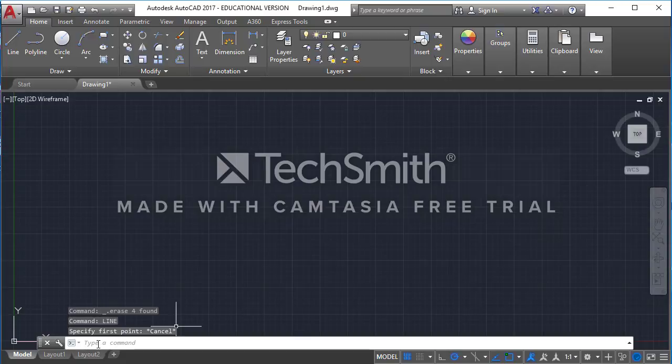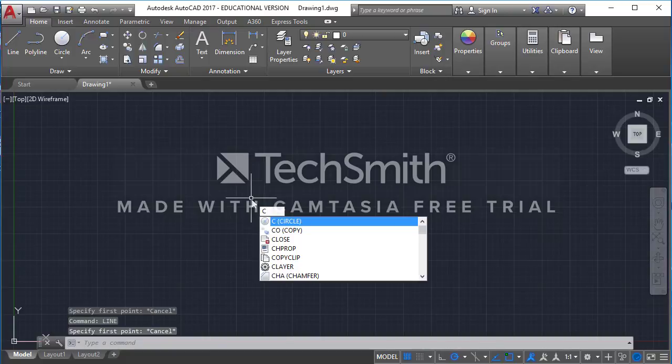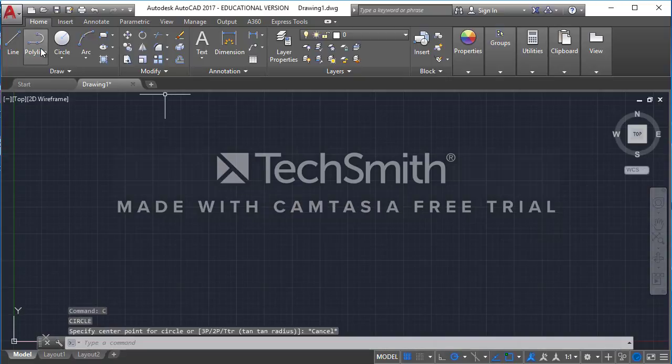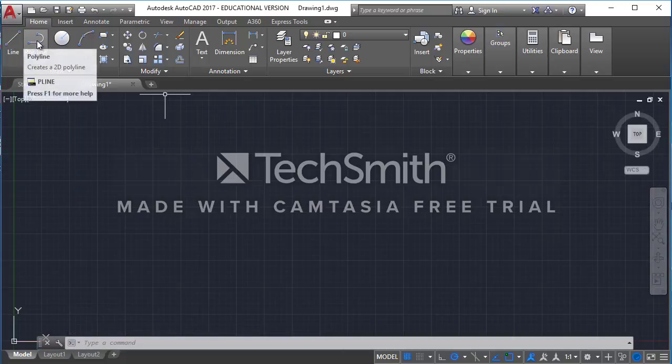Okay, so that's going to be our typing command. You do not have to click on this actual bar to start using it. You can just start typing at any given point, and the command will get going. For example, type in line, enter, and it will start to let you create that line. I can type in C, hit enter, and create a circle. If you hover, actually I don't know if this does it like Revit does. Oh, it does.